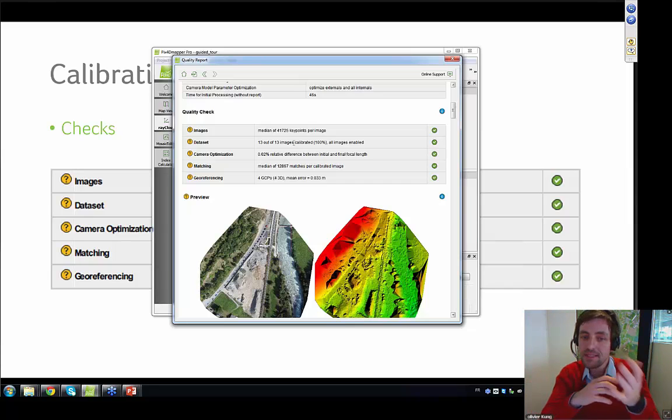The second one is giving you the number of images the software was able to position. If you have some missing images, well, if it's just a very little percentage, normally this has very often zero effect. But if you start to see some larger amount, like 5, 10, 20%, this is a good indication that something went wrong in the project. Maybe the project was too complicated, too many things were moving, you were trying to reconstruct a very difficult dataset, like with trees at a very low altitude, or the overlap was not enough. So this is definitely something that should always be green if you care about accuracy.